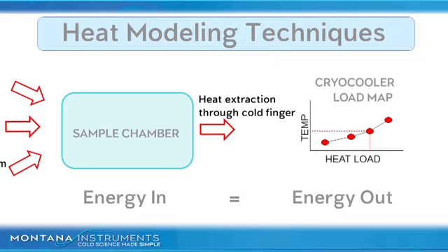By knowing where we are on the curve and what modifications we make to the system, like wire attachments or input laser power, we can estimate the operating temperature under our experimental load conditions. An easy way to measure the status of the system is to input a known amount of heat and measure the temperature response. Once we know the system temperature rise in response to a watt of power, we know where we are on the power curve for the system.